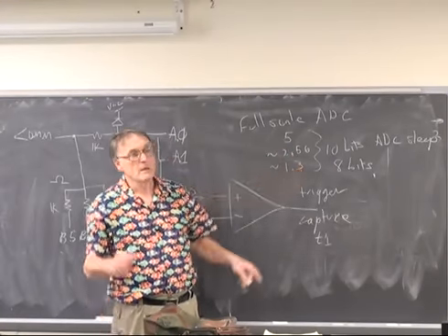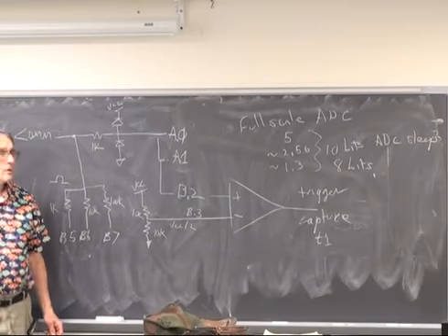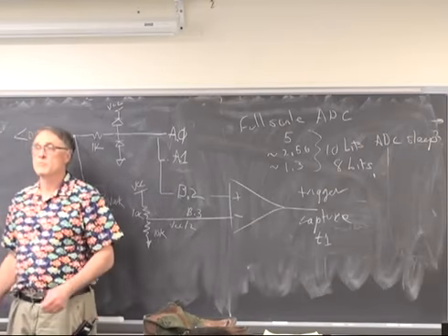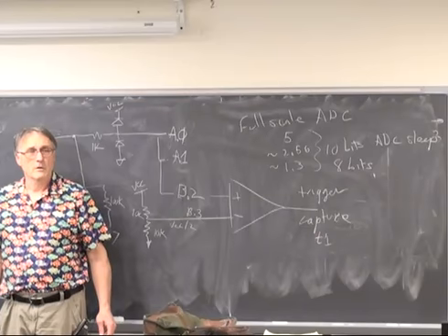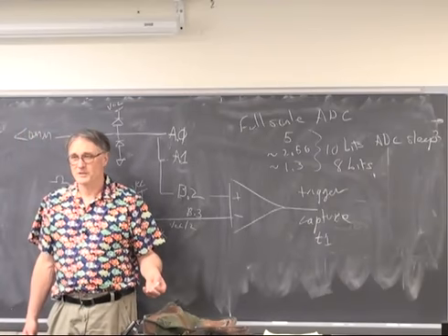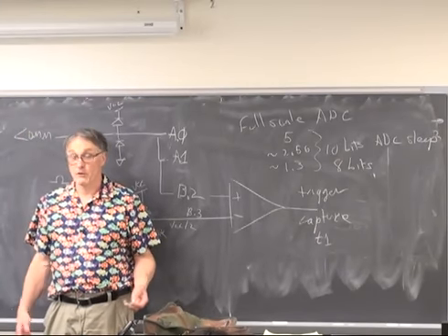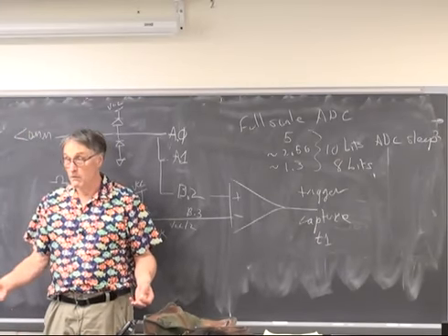probably. I'm still a little confused, but when do you change the actual pre-scaler value for measuring the frequency, auto ranging the frequency? Well, let's say that you start at some random pre-scaler. There's 3 possibilities. One is you measure no counts at all. Uh-oh. It's too high a frequency. It overflows. Uh-oh. Or it's just right in the middle.